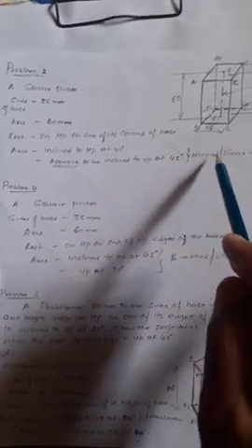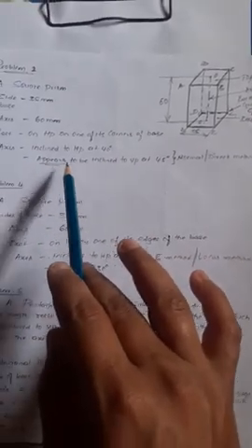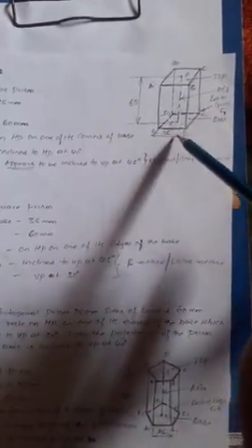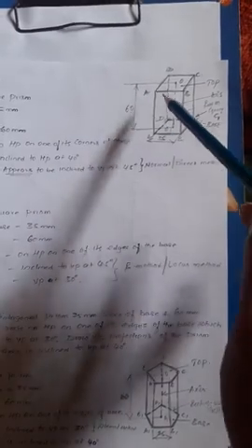The axis appears to be inclined to VP at 45 degrees, which means it comes under the normal or direct method, because the word "appears" is there, so you can draw it directly. As you know, the solid is a square prism. The base is given with side 35 mm, the base is square and the top is also square. The axis is 60 mm.